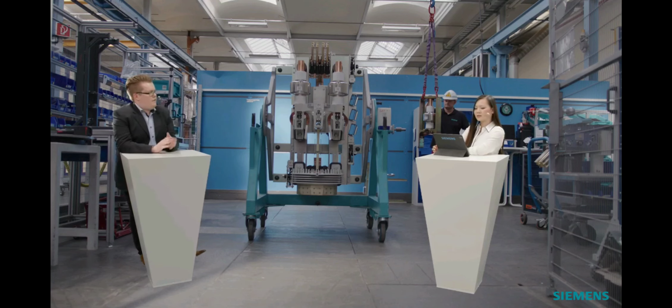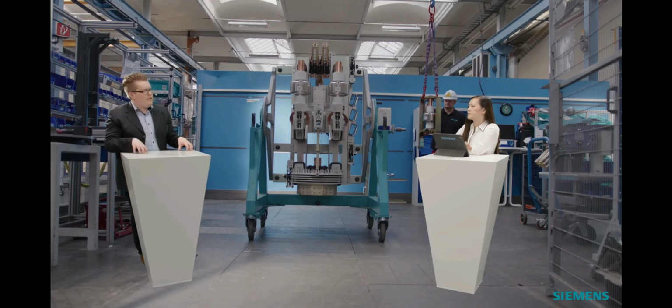All right. Another question is, what is the impact of parallel generators at the same bus bar? Is it covered in this estimation tool? This is also not covered by the estimation tool, but it can be simply calculated. Important is to know the total amount of generated power. So let's imagine we have not only one generator, but maybe 2, 3, or 4 generators. We have to calculate the short circuit current of each generator.